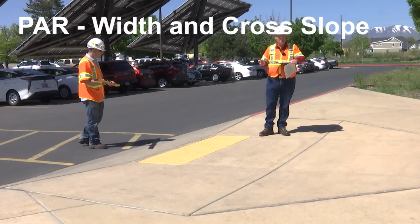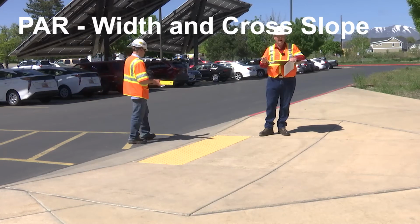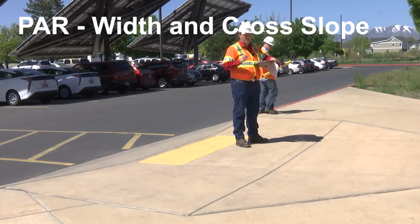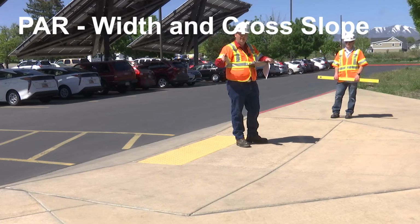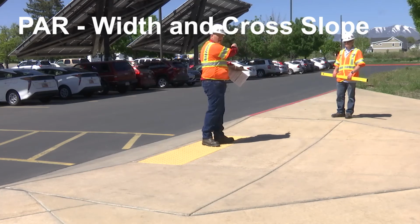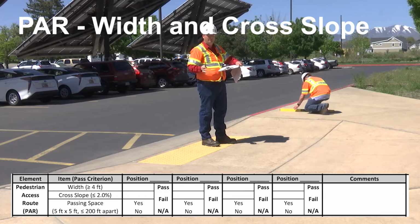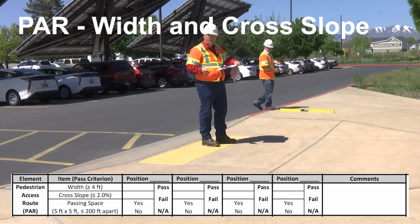Next is the pedestrian access route width and the cross slope of that. So we'll look at our pedestrian access route. Where is our pedestrian access route? Well, we come to our ramp, we come to our turning space, and then we have the option. We can turn and go that way, or go straight, or turn and go that way. So we have 3 different pedestrian access routes. We will measure the cross slope at each of those routes and the width to make sure that we have a minimum of 4 feet.